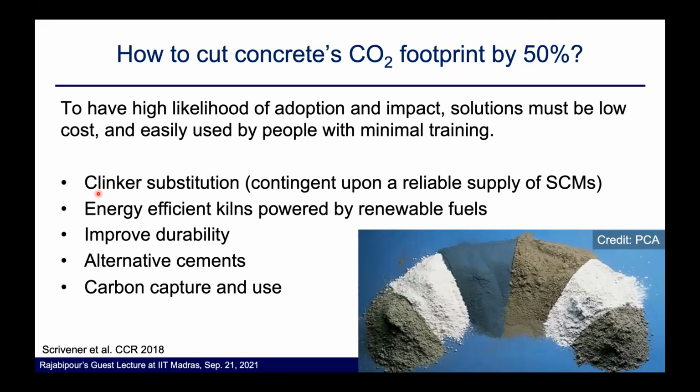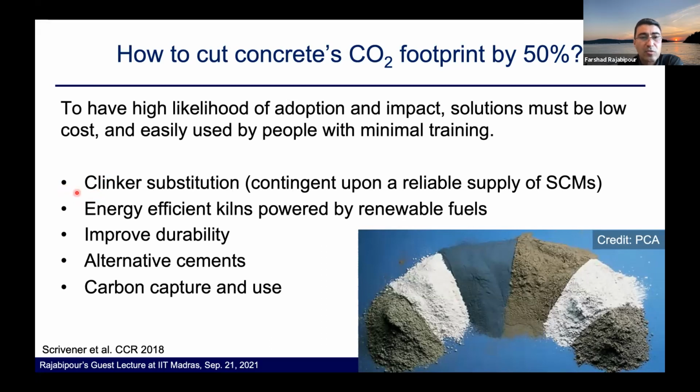Others, and the rest of my talk really maneuvers on this point quite a bit. Other solutions that have been suggested are energy efficient kilns that are powered by renewable fuels, improving durability of concrete, so we're reducing the demand for renewing the structures or building structures frequently, alternative cements using geopolymers, calcium sulfoaluminate cements, and so on, and also carbon capture and use technologies like CarbonCure, Solidia cements, and others that use CO2 curing and sequestration inside concrete.